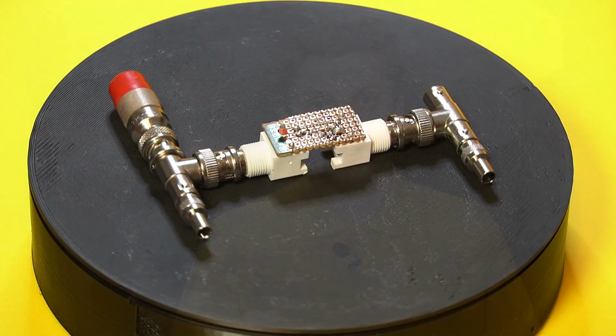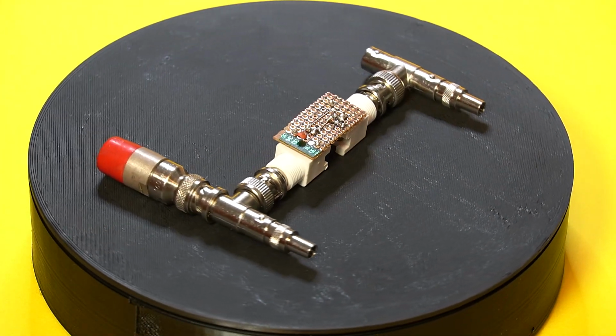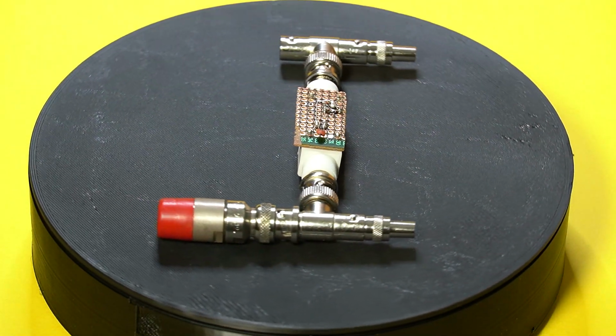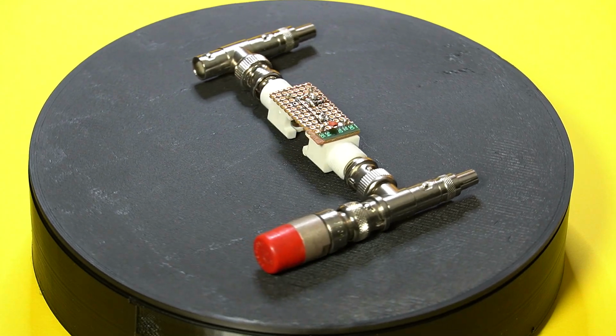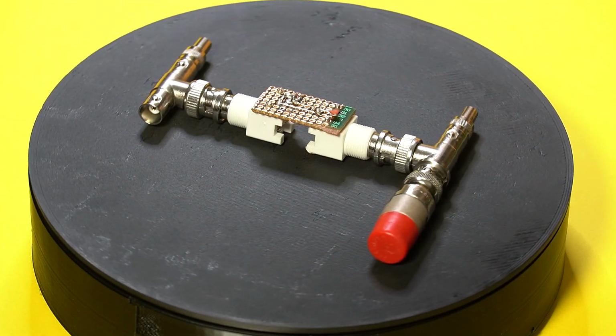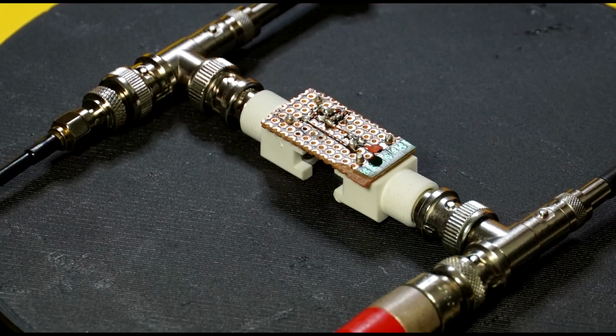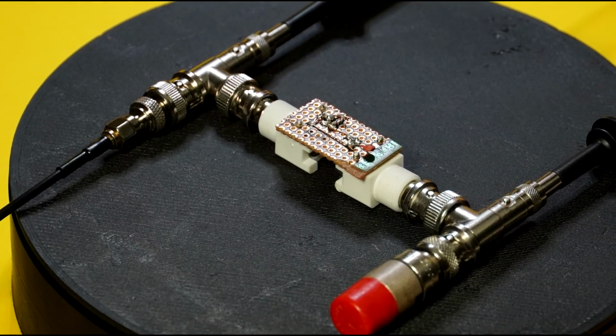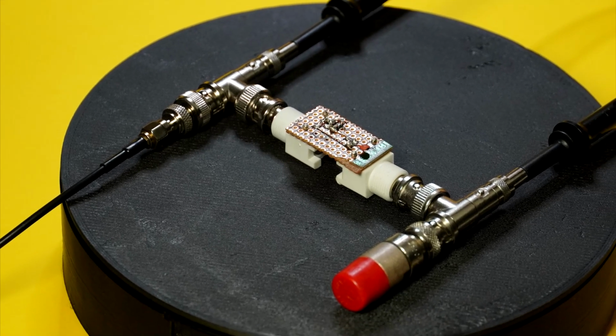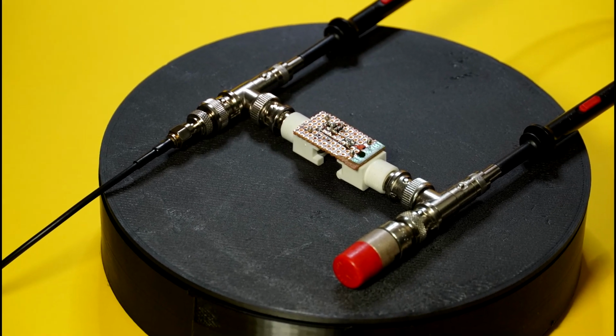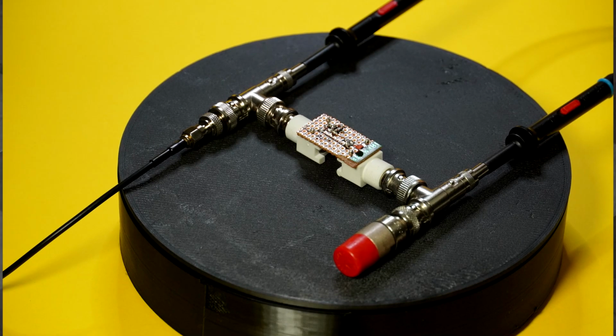So finally, let's try an experiment and apply these principles. For that, I prepared a tiny board with dual BNC connectors to which the various components will be attached. One side will be connected to a 50 ohm signal line and the other to a 75 ohm termination. And to perform the measurement, I will be using 10x oscilloscope probes, which will add some parallel capacitance that is not negligible at the 50 MHz at which the measurement will be performed. So I will try to measure the impedance of the signal source and the load, but also compensate the oscilloscope probe capacitance that's being added.